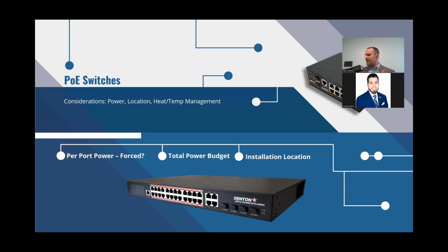I'm sure you guys have seen a PoE port, if you try and draw too much power, drops off the port. Because of the nature of the lighting and type BT type PoE, you have to make sure you use a PoE switch that is reputable and good for that type of power.